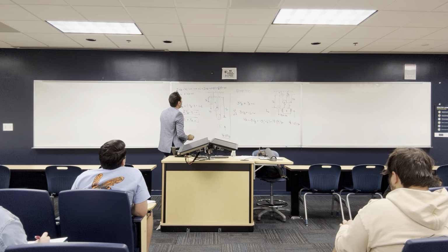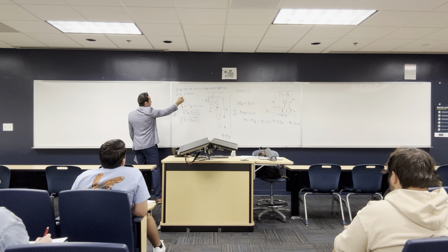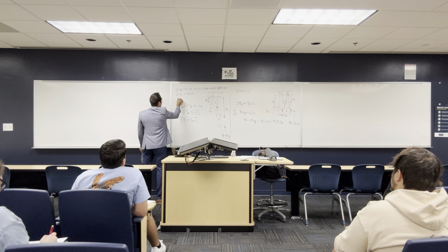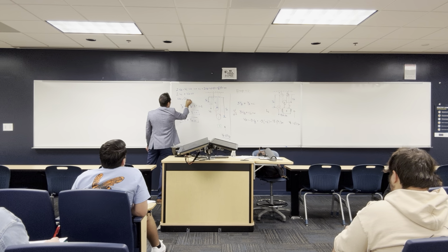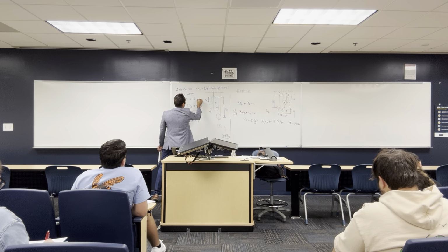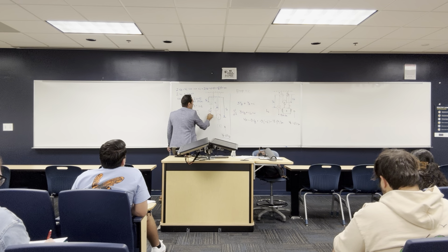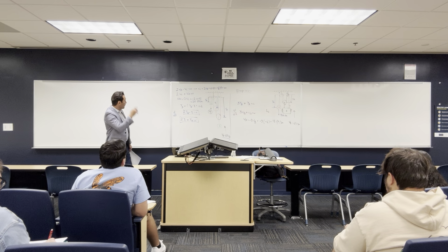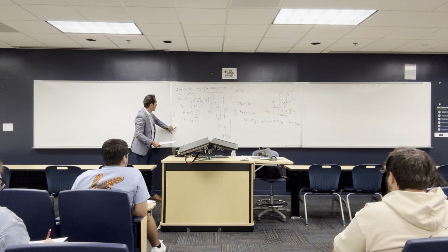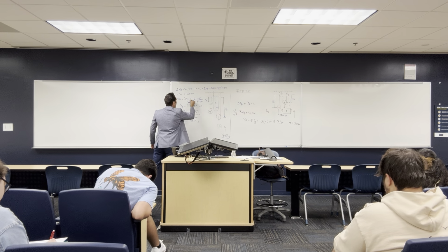All right, so how about A? I have already vC is negative 12, so I have vA is equal to negative 2 vC, and this is going to be negative 2 multiplied by negative 12. This is going to give us 24 feet per second. And it's positive, that means it's going down, so everything should be right. Okay? We'll just put these equations up so that you all can see the answer. So already I got vA, which is requested in this problem.